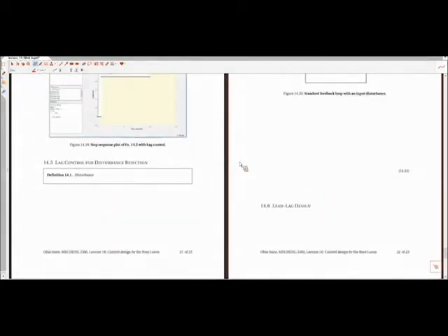Okay, so also, just like it was discussed in PI control, it can be used to reject disturbances. So I showed the example, I have the system on my desk up here. I showed that if I were to take my hand and start to crank on the inertia, that would actually fight me. So same idea, that was PI control fighting you. Same idea with lag control. It can be used to counteract some sort of disturbance.